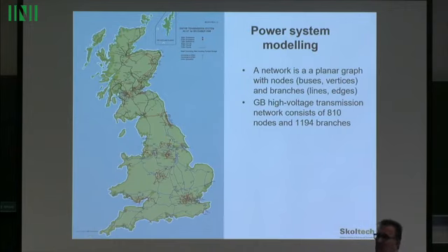Voltages, well, you know that we've talked about it, that the higher the voltage, the lower the transmission losses. It means when it's transmission, you go into hundreds of kilovolts, for example. The reasonable numbers would be about 100, about 200, about 300, and about 400. But why is it, for example, this country is 275 and 400, and Europe is 220 and I think 440, I can't remember at the moment. It's just a matter of judgment, normalization at a certain point, and that's a kind of similar range, although they may not be exactly the same.